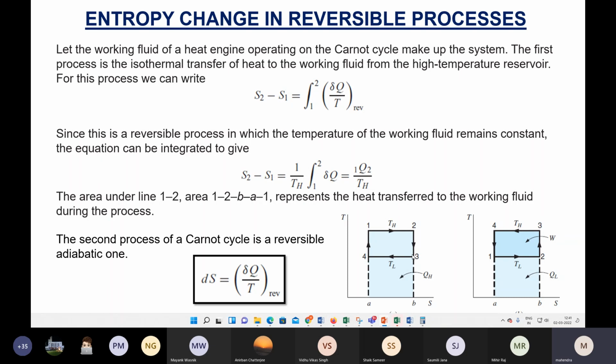Then this is the condenser, working at constant pressure, heat rejection, constant temperature, simply phase change. And this is the pump, which we have also considered adiabatic compression. This is adiabatic expansion, and this is adiabatic compression. An adiabatic process is an isentropic process, so this is also a vertical straight line. That way you can see the Carnot cycle in a different shape on your TS plot.